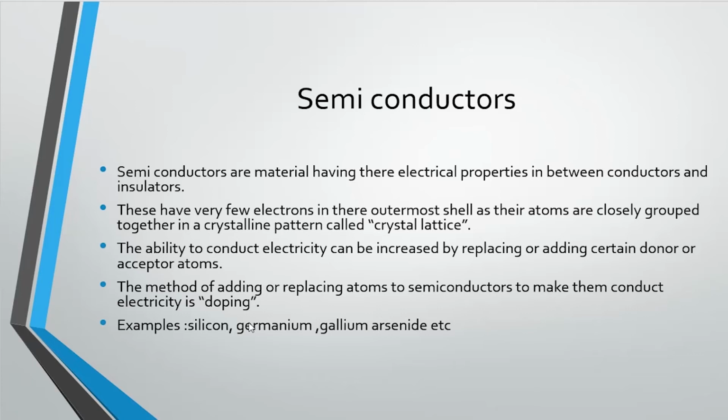But silicon being the most intrinsic semiconductor, that is, chemically pure, as I mentioned, containing nothing but semiconductor material. By controlling the amount of impurities added to this intrinsic semiconductor material, it is possible to control its conductivity. The process by which we do this is obviously doping.